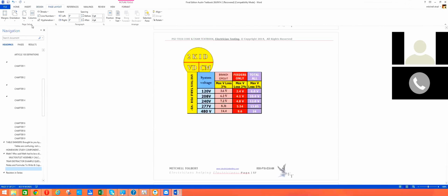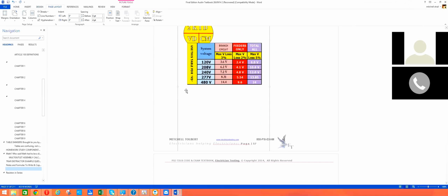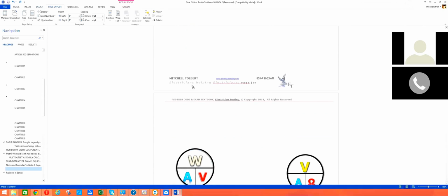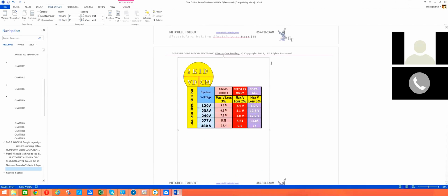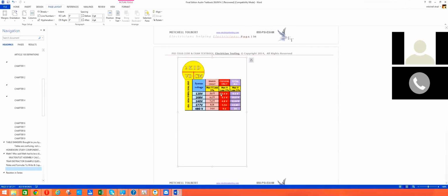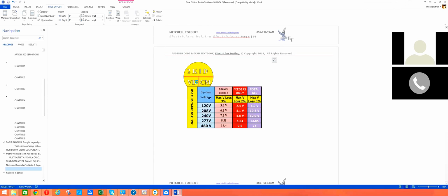Yeah. Do you remember any of the voltage drop questions you had, or any of the specifics? They were kind of just like what you had asked when you were writing that one out, but they had the constant. It says use this constant in parentheses for copper or aluminum. Yeah, the 12 something for copper. The 12.9.